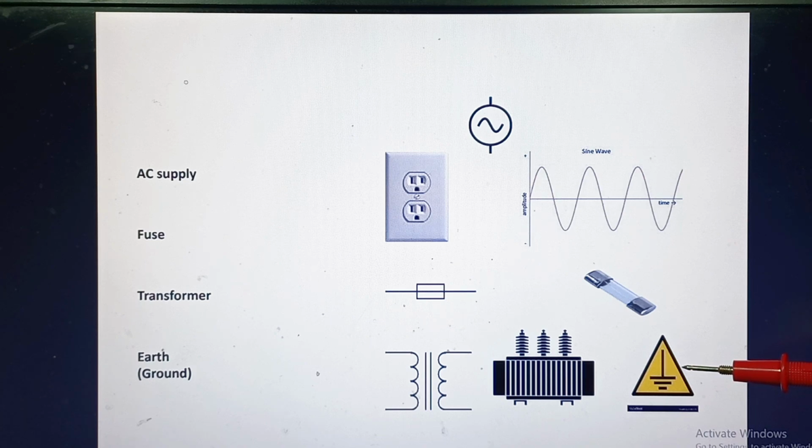Exposed conductive parts of electrical equipment are connected to the ground to protect users from electrical shock hazards. Connections to ground also limit the build up of static electricity. For measurement purposes, the common ground or earth serves as a 0 volt potential reference against which other potentials with polarities, positive or negative, could be measured. It is called the 0 volt reference point or common ground for all return paths of an electrical circuit.